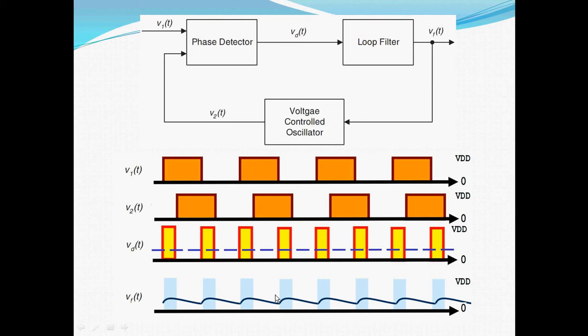After some delay, the loop filter would also produce a non-zero signal Vf, causing the VCO to change its operating frequency in such a way that the phase error finally vanishes, and after some time, the VCO will oscillate at a frequency that is exactly the frequency of the input signal.